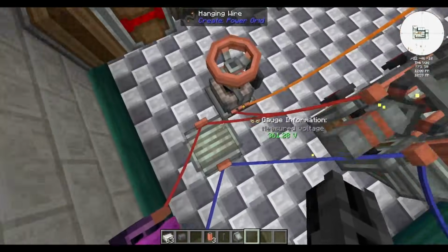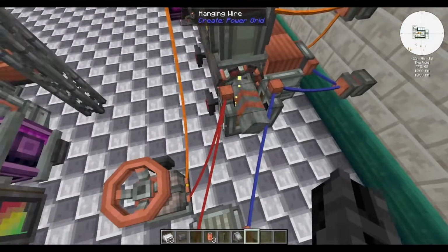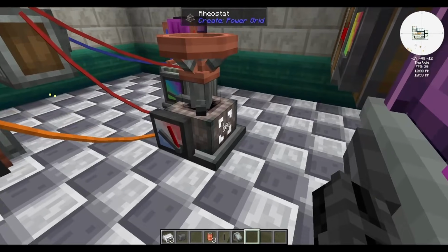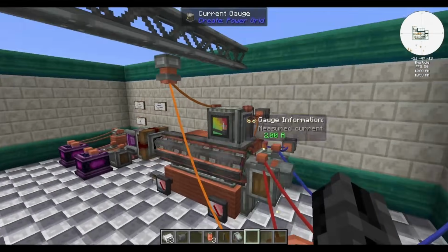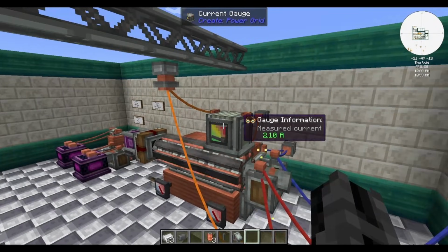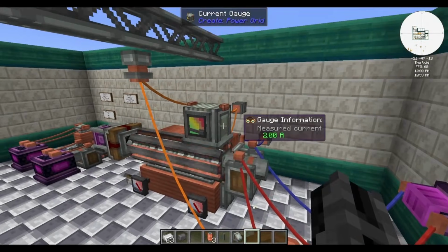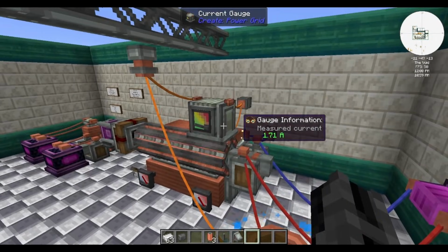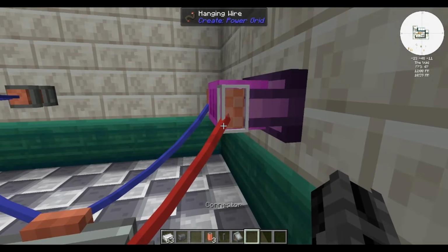And now the circuit for the exciter coils is just a rheostat connected in series with the minimum resistance set to 200 ohms. So we may adjust the current flowing into the coils by adjusting the rheostat. If we go below the excitation current, the power drops.